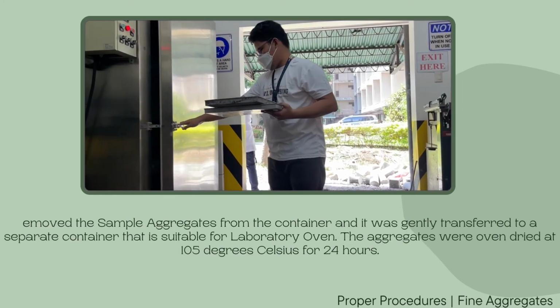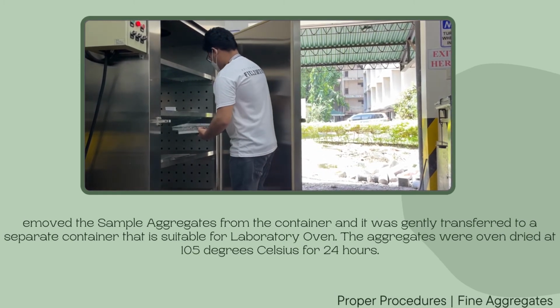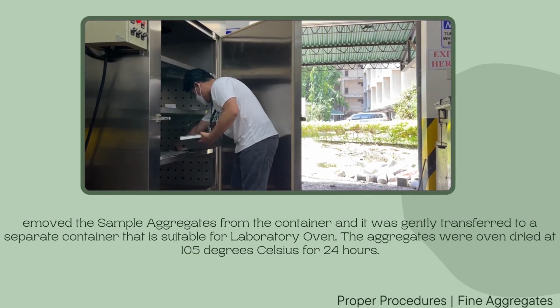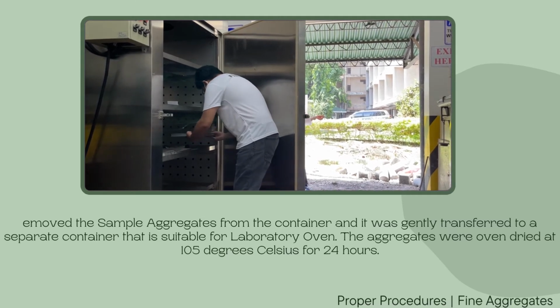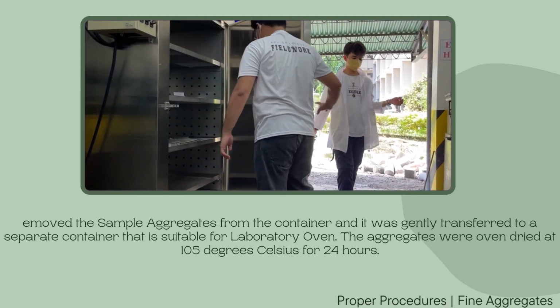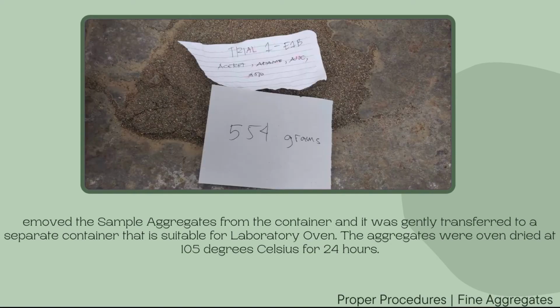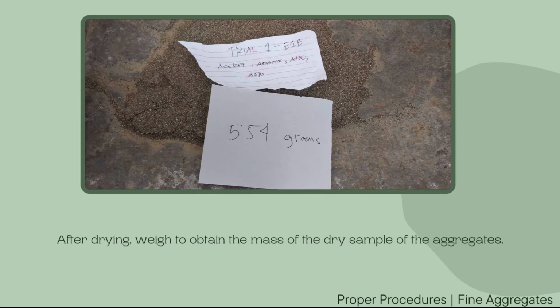Sixth, the sample aggregates were removed from the container and gently transferred to a separate container that is suitable for a laboratory oven. The aggregates were oven dried at 105 degrees Celsius for 24 hours. Seventh, after drying, weigh to obtain the mass of the dry sample of the aggregates.